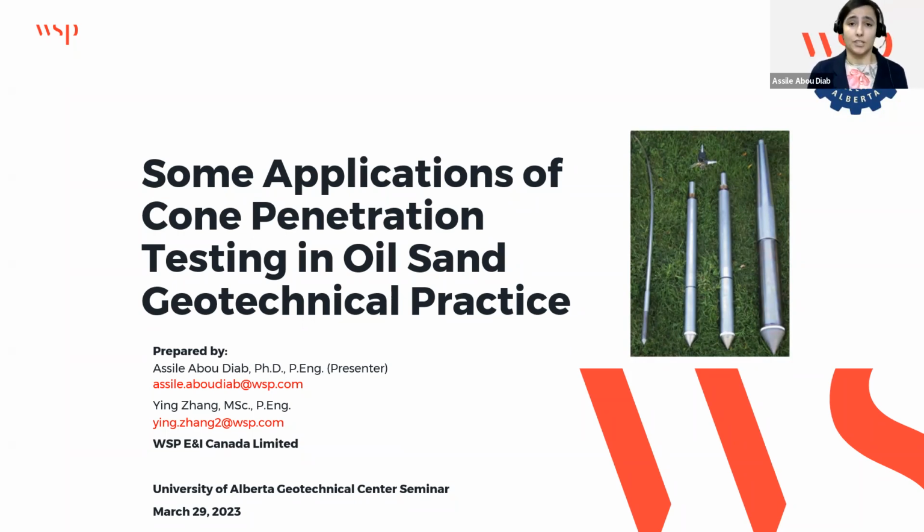So what is cone penetration testing, CPT? As we see here, a CPT is an electronic probe instrumented with transducers and load cells and is connected to a series of 1 meter hollow bar tubes. The whole thing is pushed down the soil at a constant rate. While it is pushed, it measures the axial force on the cone, the friction on the sleeve, and the pore pressure on a transducer that's usually mounted behind the cone.